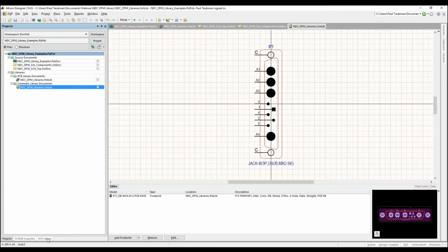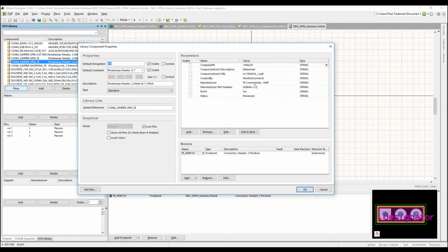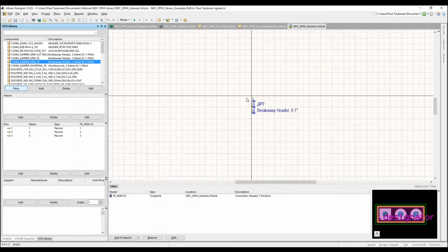Now, the big thing I find with libraries is that you need to have consistency, because consistency gives you your feel and look of your libraries. And really the biggest problem I find with consistency more often than not are blanks, and not just really following what you put over here and filling in the blanks. We'll talk about this, which I call intelligent data, but also making sure that the information that you have over here as well, especially for your pins, looks the same. Like, for example, you're not changing different fonts, you're not doing different font sizes, and so on and so forth.